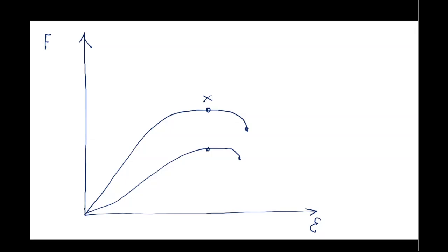The neck will shrink the cross-sectional area and less force is required. Therefore, the force at fracture will be less than UTS. Okay, so as long as the force at UTS is larger than the force at fracture, you'll be fine.